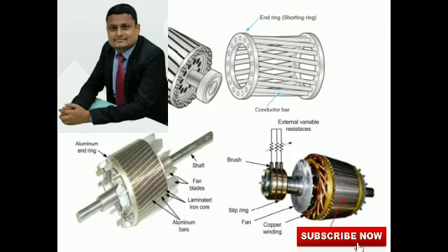So now rotor current through rotor bars, that is conductor, IB equals 6 into IS into TPH upon SR into KWS into cos phi. IS is stator current per phase, TPH is stator turns per phase, KWS is stator winding factor, and cos phi equals power factor. Once again I am repeating, IB equals 6 into IS into TPH into KWS into cos phi divided by SR.